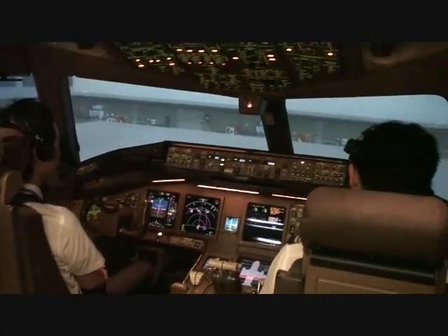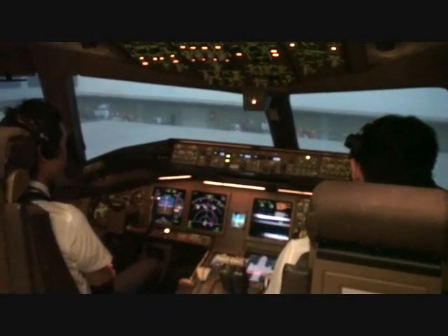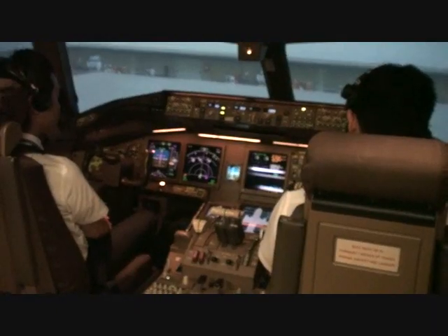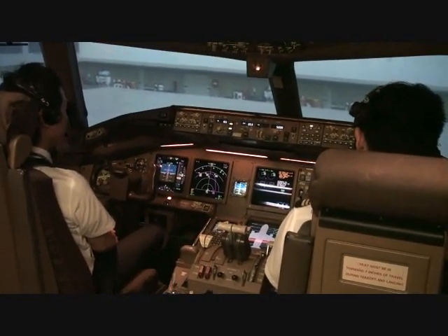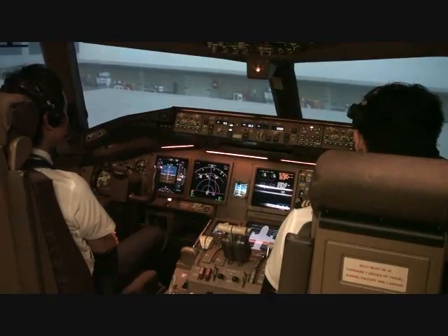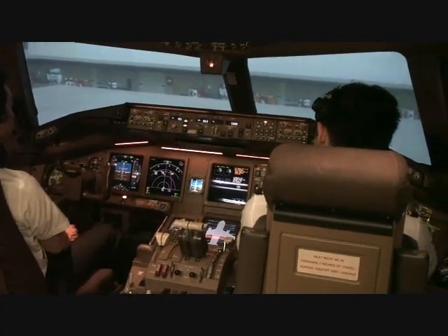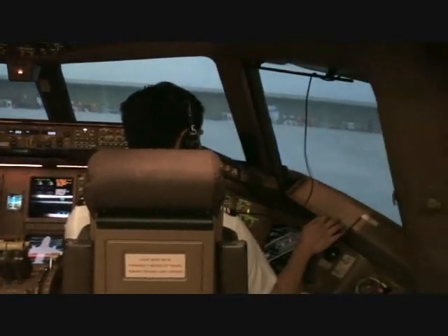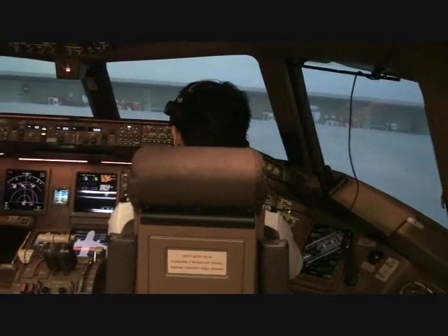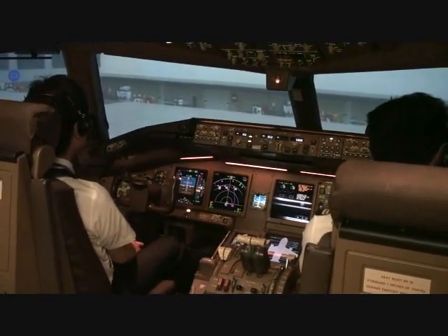CDU display, CM1 and 2. Normally PF selects the takeoff reference page. Normally PM selects the legs page. Exterior doors, verify closed. Flight deck windows closed and locked. Verify that the window not closed decal does not show. Verify that the orange indicator does not show.